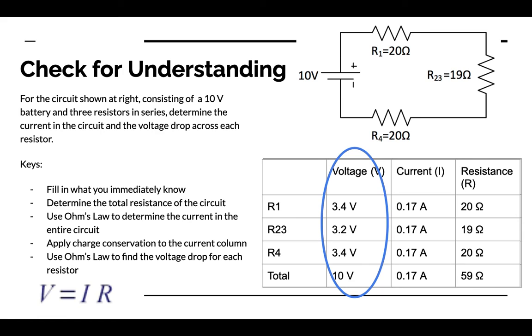If you look at any component, any electrical appliance, they often have an input voltage and an input current, and that tells you the maximum amount of current that can be passing through that component, and also tells you the voltage required for the electrical component to work. So if these electrical components hook into a circuit like the resistors do, then we need to be able to calculate, if we hook these electrical appliances into our circuit, what is the current output going to be in the circuit? Will that be enough to power our devices? Will it be too much to power our devices?